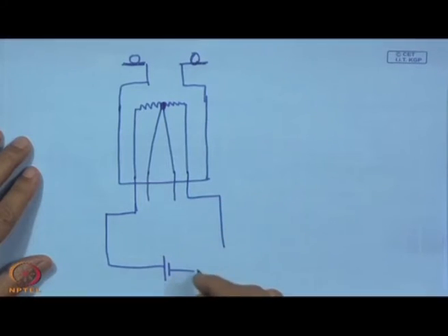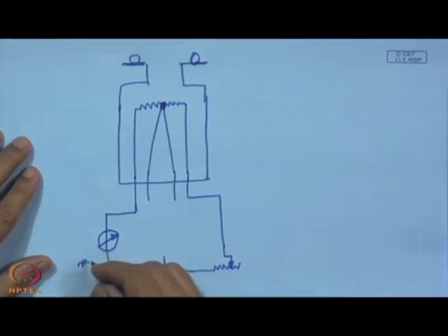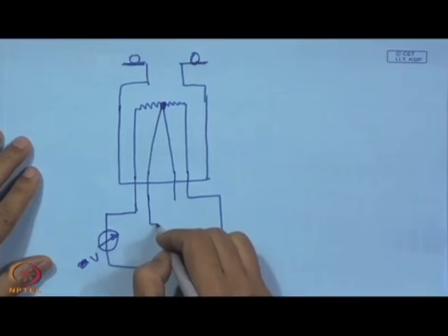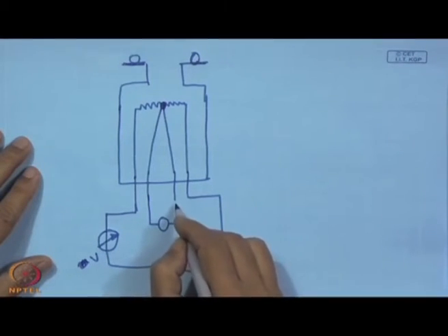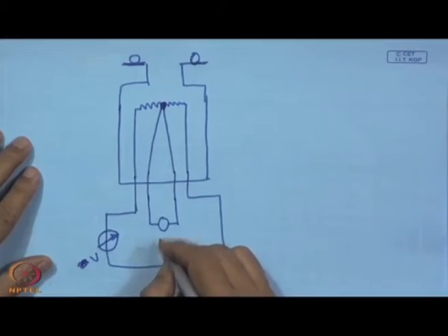So, here we can change the power supply, and here perhaps we have one meter, and this is in millivolts. This is volt, and here we can see the reading because of this thermocouple, and that may be the millivolt thermo EMF which can be generated.